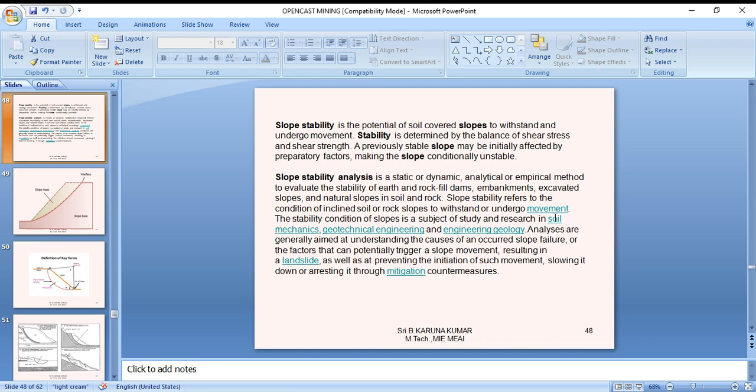Slope stability is very important; most of the recent accidents observed in Myanmar and at Northern Coalfields Limited, even in open cast mines and some single benches, are slope failures. They occur because the proper inclination was not maintained or designed before the operation started. So that example shows slope stability.